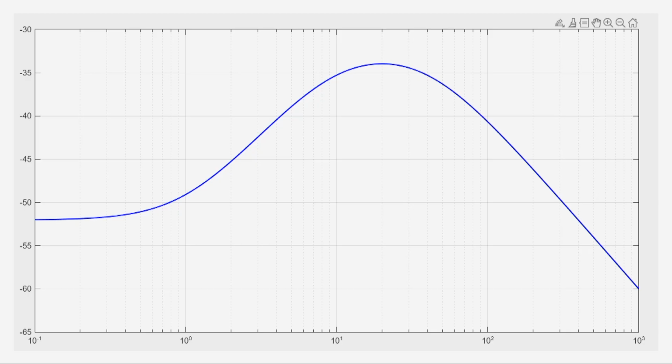Suppose you ran an experiment and the data that you got was this, which is basically for different frequencies you got the magnitude in dB scale. This is the magnitude plot that you got. How can you experimentally find this? As I have already said, you have to just give different sinusoidal inputs to the system, and based on that you have to check what is the output and measure the magnitude and phase. We will see soon in this lecture itself, at the end, how to do that.